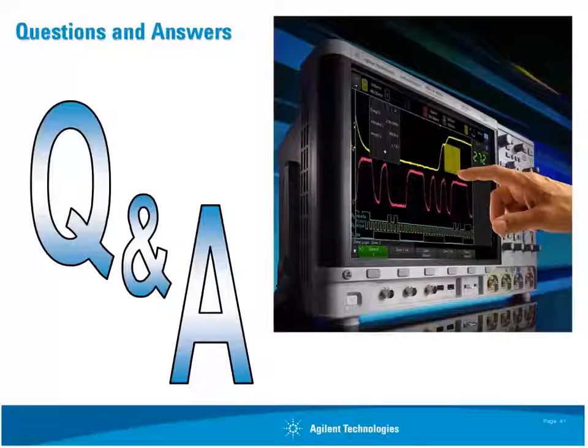So how is it possible to reduce a scope's update rate? Okay, I did show one example of the scope updating at 1,000 waveforms per second, and another example updating at its maximum rate for that particular setup condition. The way I did it in that example is most scopes on the market today have what's called a trigger hold-off capability.